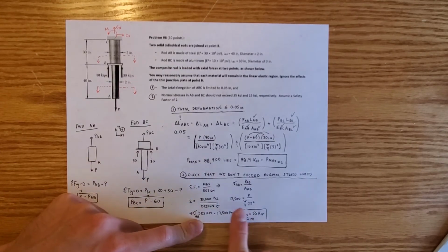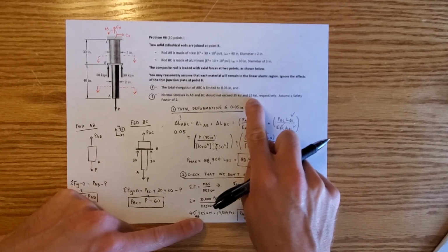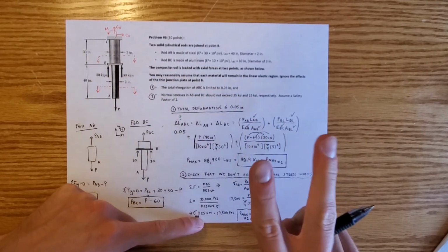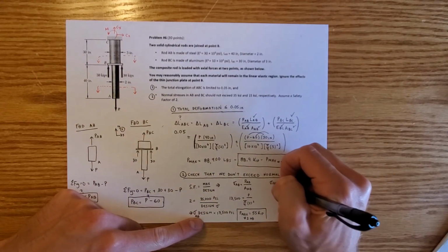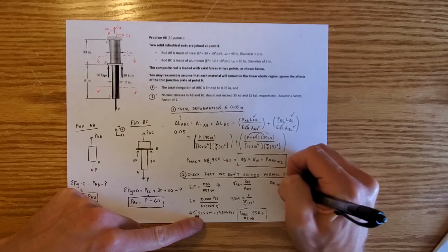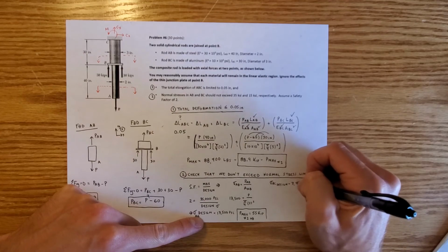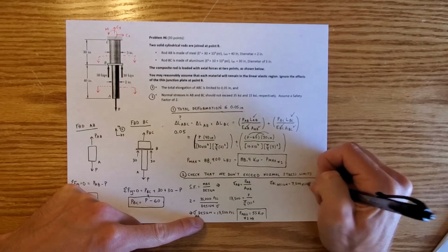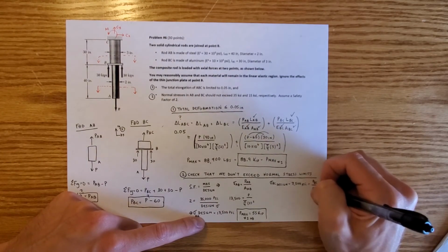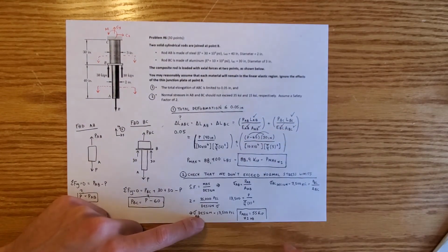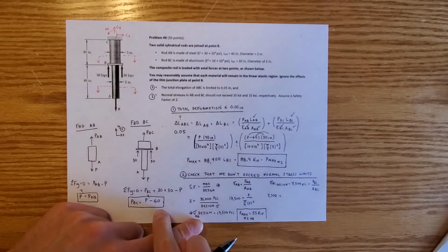Following the exact same protocol here, what you can see is that if our sigma max for BC is 15 KSI, with a safety factor of 2, we'll follow the same exact procedure, and you'll find that sigma BC design, our limit, is equal to 7.5 KSI, or 7,500 PSI. And we'll set that equal to PBC over area of BC. Now we know that 7,500 will equal this now instead of PBC.